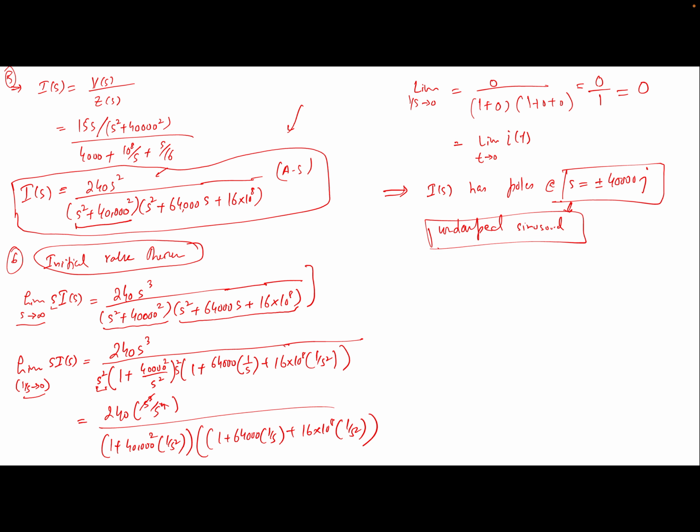Okay, cool. So once we did that, now I have to find i(t). Let's do the final thing. I am interested in finding my beautiful function i(t). In order to find i(t), I need to solve this I(s). And the problem with solving this I(s) is I need to convert that into partial fractions and then solve it. Maybe I can do that on the next slide.